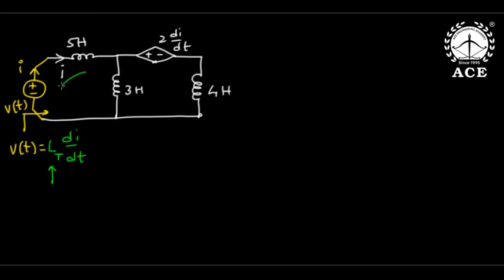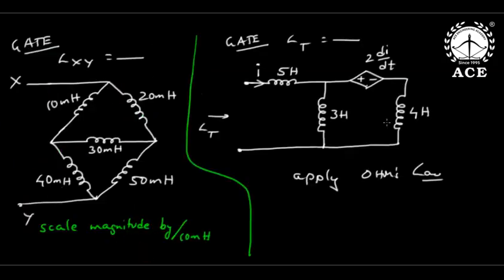Now listen, sir. This input current itself is the mesh current I, because it is the source driven current. So this I, I will take as I1. Here it is like Thevenin's category 3. I cannot give DC. If you give DC, then all di by dt is 0, then the dependent voltage source is also 0, short it, then all inductors are shorted.